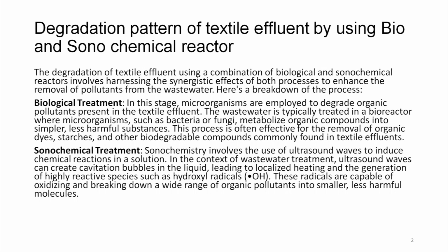Sonochemical treatment. Sonochemistry involves the use of ultrasound waves to induce chemical reactions in a solution. In the context of wastewater treatment, ultrasound waves can create cavitational bubbles in the liquid, leading to localized heating and the generation of highly reactive species such as the hydroxyl radical. These radicals are capable of oxidizing and breaking down a wide range of organic pollutants into smaller, less harmful molecules.